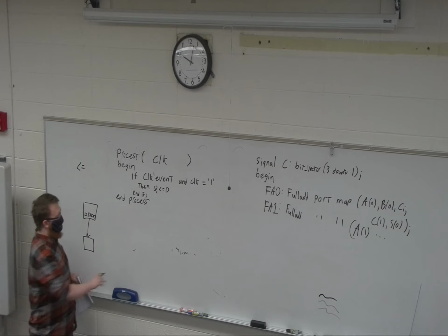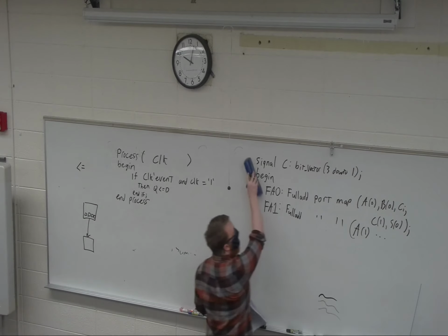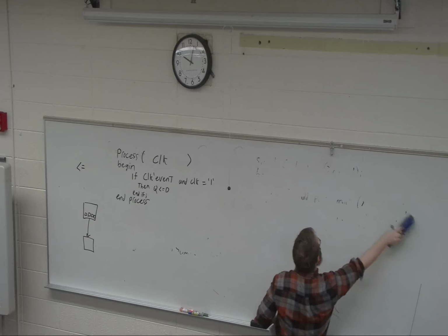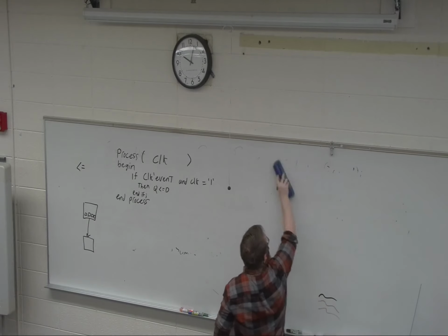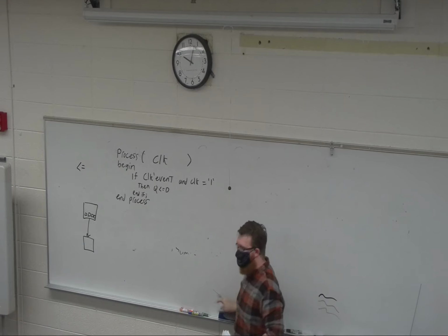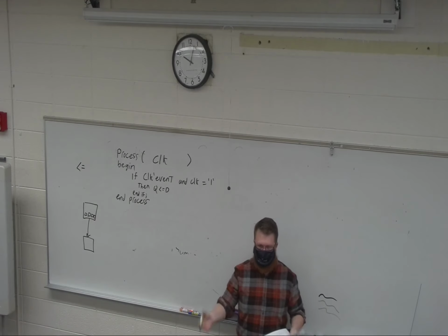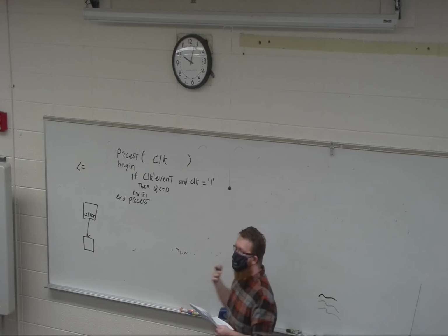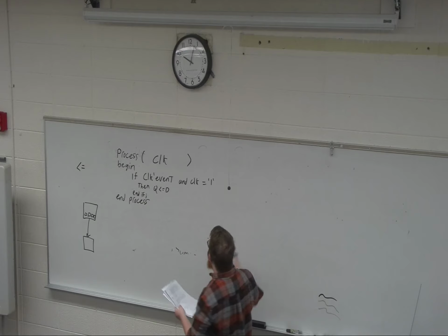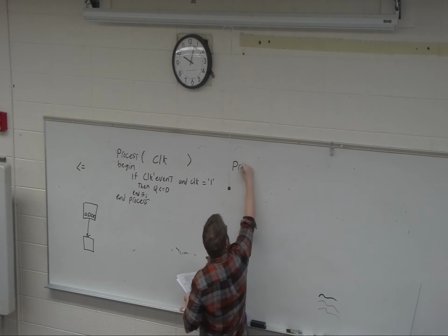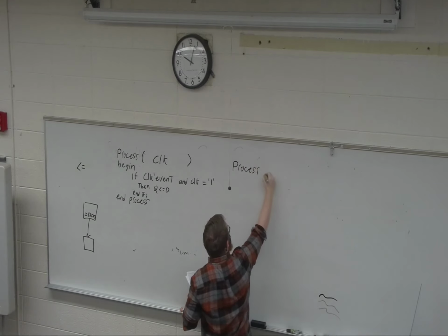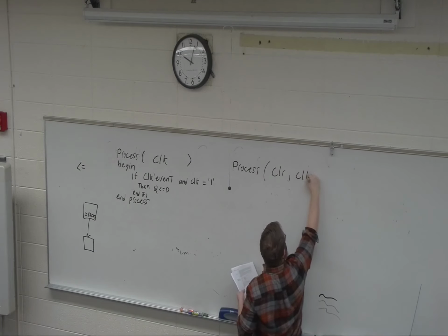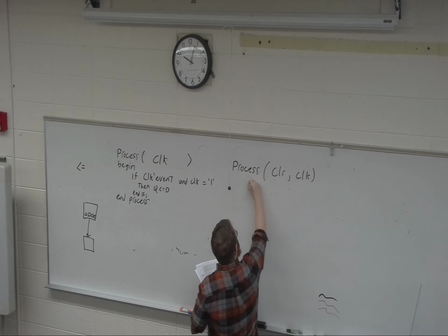There's another idea that we will use very frequently, especially when you're writing in flip-flops, which is the asynchronous clear. So your flip-flop is going to be synchronous, right? It's going to update on clock edges. But your clear can happen anytime. So I can make the change and say there's now a clear and a clock, and that if